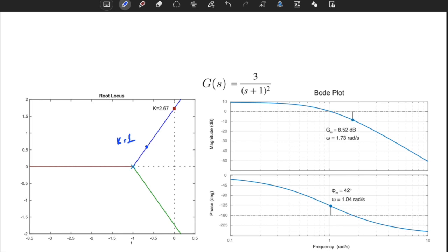It's an important margin, and technically, if you don't label this k on the root locus, it doesn't give you this important metric. It's a different metric than, for example, looking at the distance with respect to the imaginary axis, which gives you settling time, which is important, but it's also important to measure the margin in terms of increasing the gain such that I'm still stable. So, this is my critical case. My gain margin is technically equal to